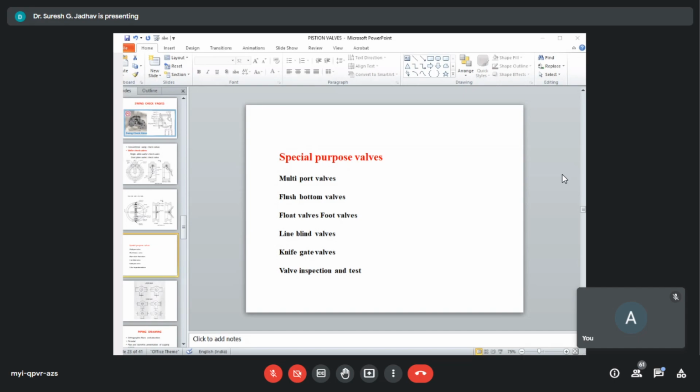The lever length could be adjusted to suit the level in the reservoir. These valves have threaded ends and are connected to the wall of the reservoir with hexagonal nuts. The reservoir need not be provided with nozzles. Only an opening is required. The level of liquid will always be below the inlet connection.